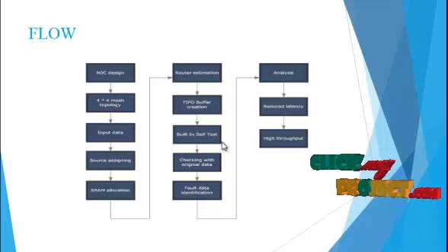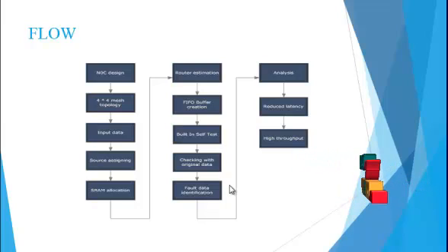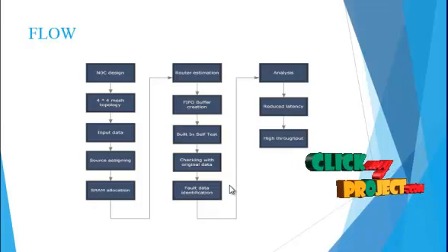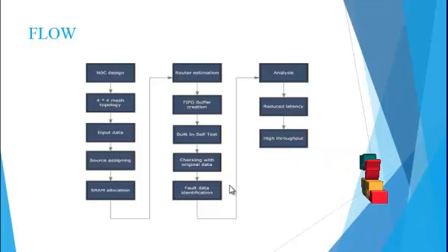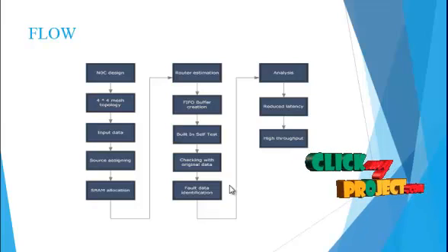It will check the original data against the fault detection data. For example, if we have given the data as 10101010, that is 8-bit data, it will complement the data to produce the fault data, 01010101.